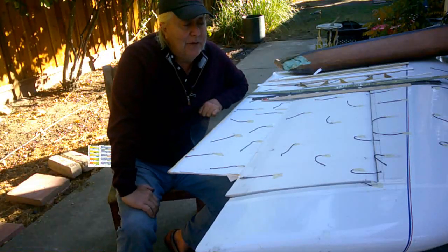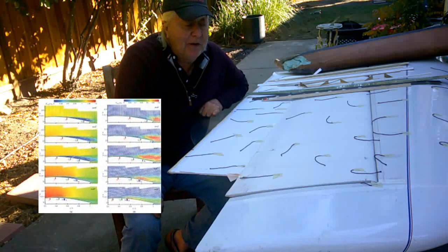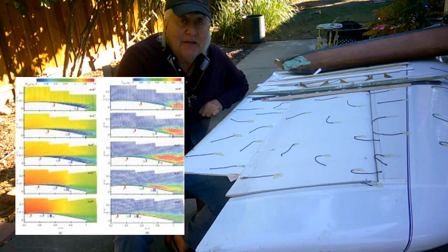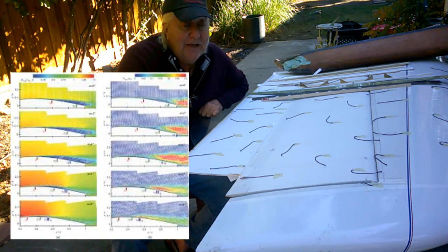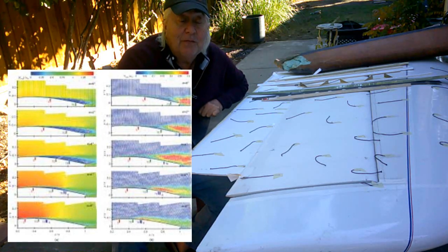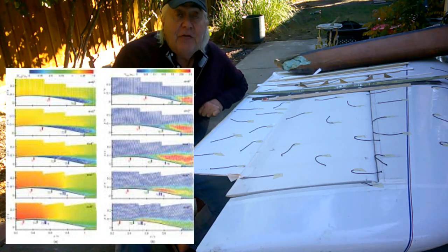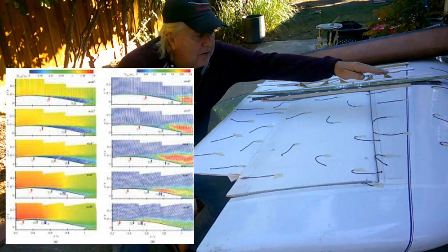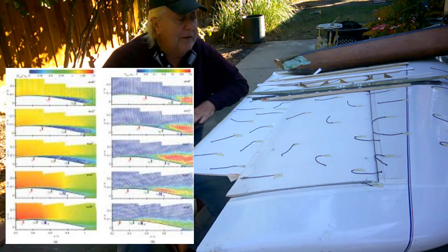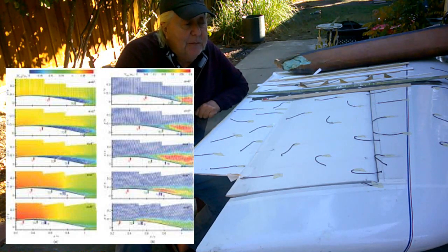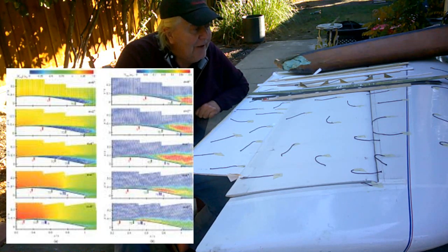Okay, welcome back. We took a look at some of that crazy flow and saw stuff that's indicative of laminar separation bubbles. And hopefully, if I remember, I'll have put up some pictures of the theory of laminar separation bubbles, where they occur, because they can occur up front or further back and so forth. And they occur in different places at different Reynolds numbers. But they are very difficult to predict, and they have a relatively random nature.